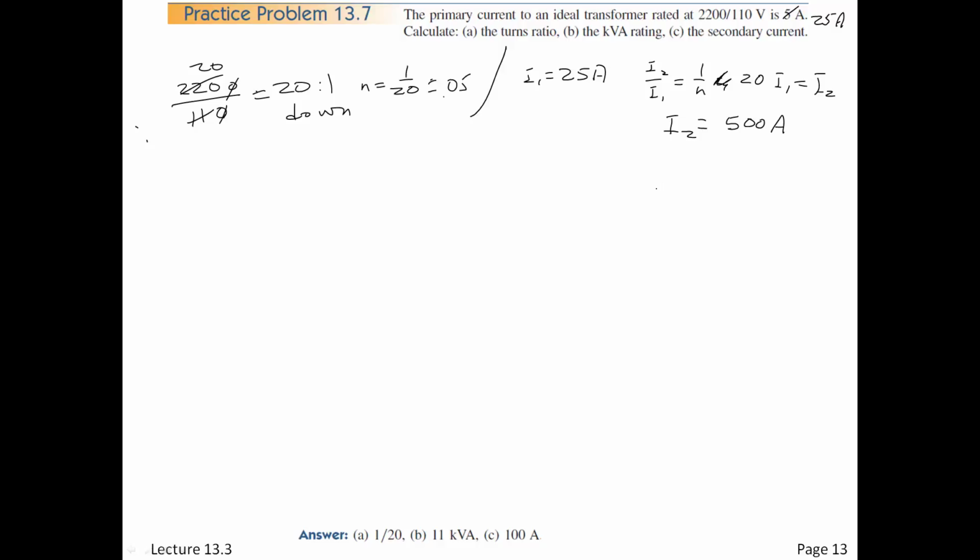Okay, remember, power is the same on both sides of the transformer. So when we stepped down by 20, the current stepped up by 20, which was a big deal. Okay, so the complex power, whoops, let's stay here. The power is V1 I1 conjugate, but that's also V2 I2 conjugate. Okay, so take it either way. And you've got what?